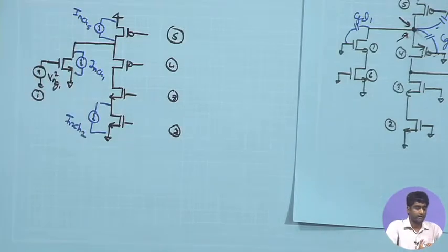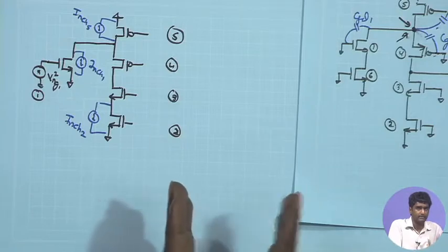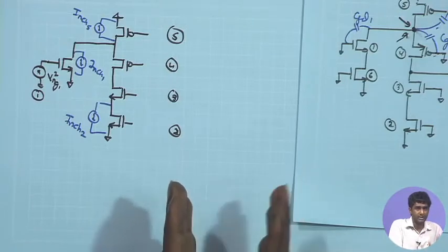So, we try to model the flicker noise as a VT shift. If you remember our discussion, the basic origin of the flicker noise is the trapping of charges, which changes the voltage drop across the oxide, and in effect changes the required amount of positive charge on the gate to balance the equal amount of negative charge in the channel.